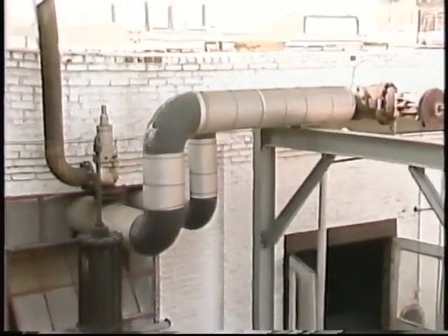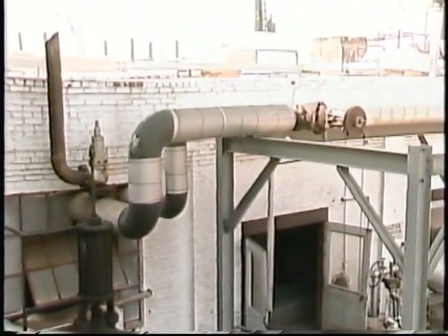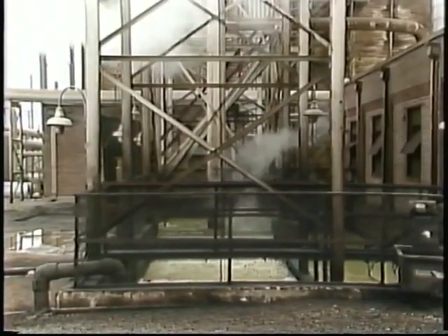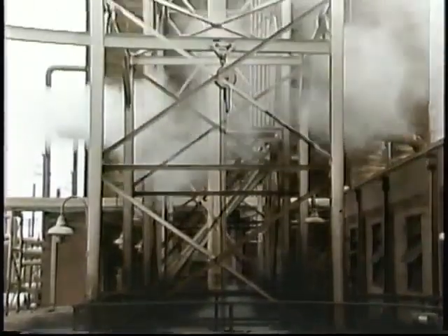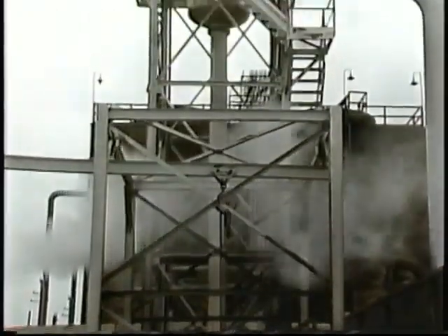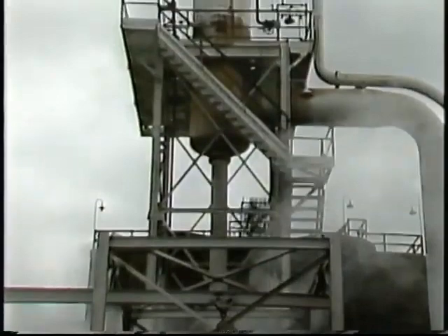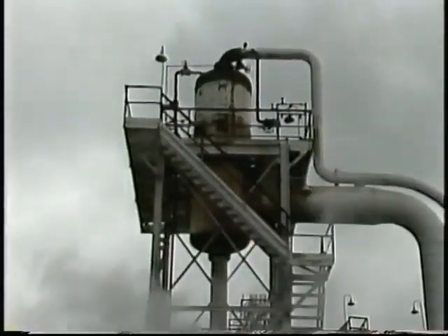In many turbines, the low-pressure steam, which still has some heat energy, exhausts to a low-pressure header for distribution for other uses in the facility. On the other hand, some turbines are connected to a condenser. In that case, the low-pressure steam is removed under vacuum to the condenser.